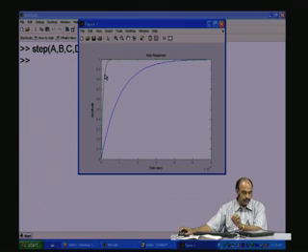Now, we have reduced the capacitance C, and therefore, the RC time constant is reduced, and therefore, this will be faster. So, you can expect it to be faster. You see that it rises to 90%, something like 0.25 milliseconds against around 2.5 milliseconds in this case. So, this is how one goes about doing the analysis in the time domain using the step response.